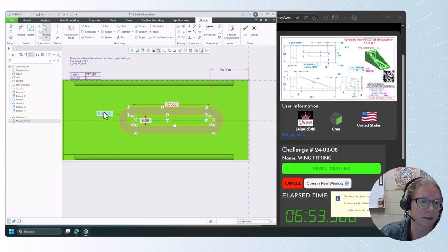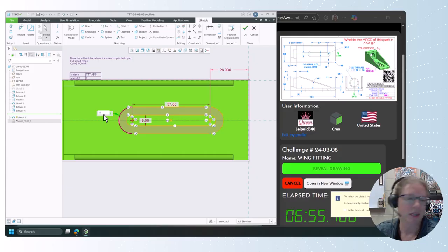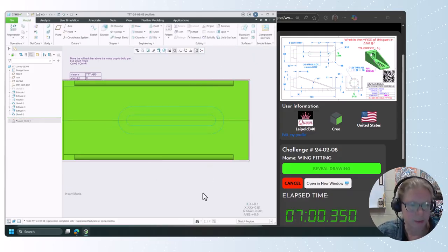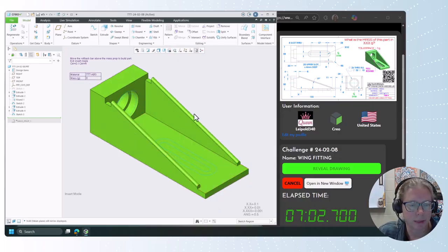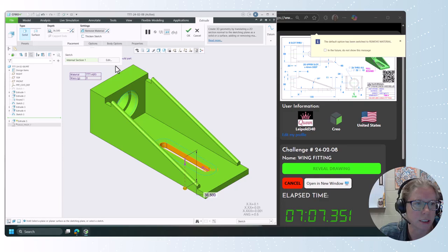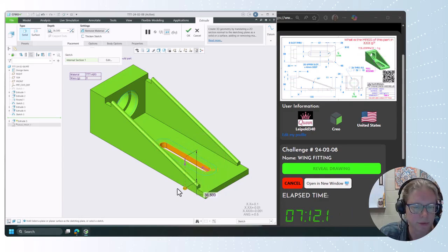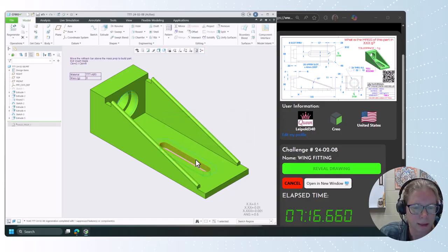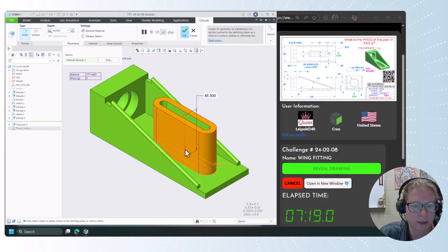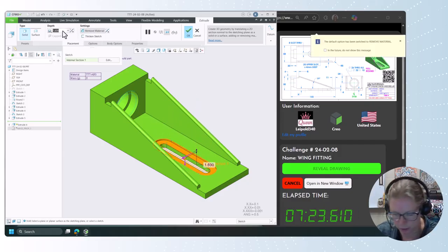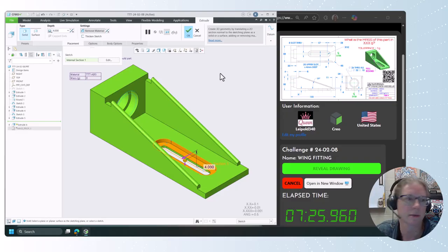That burns me all the time. I love using the filter. I always forget to unset the filter. All right, Control D. Let's turn off that plane to give me a little better sketch region. I can right click here and do, oh, no, I wasn't. There, do to next. And then extrude. And let's drag this down. And that is going to have a depth of 4, right? And that is shown right here.